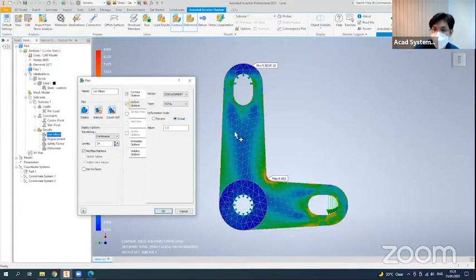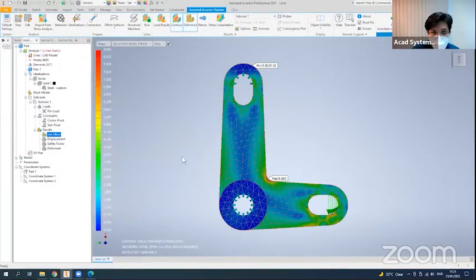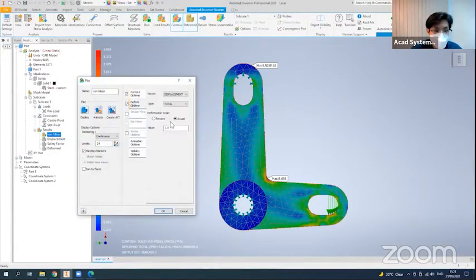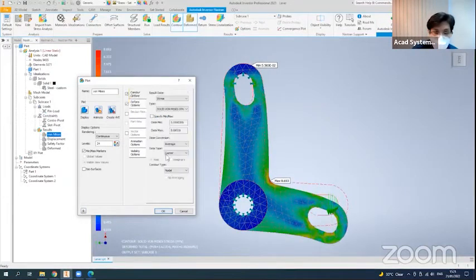This is the actual deformation. If you change your setting to the actual deformation, it will not be visible to the eye how your deformation will act. You will not know in which direction it will deform and so on. So let's click on cancel so that it does not apply the actual. Okay, let's change back to percent. Give it the original 10%.